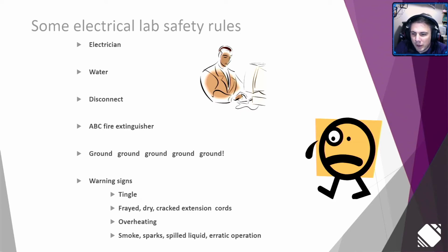And at the mine sites, if there's generally higher power, and typically in any other process areas, they just require a GFCI even if there's no water directly around it, because upset conditions happen, water spills happen, and they would just rather err on the side of caution.